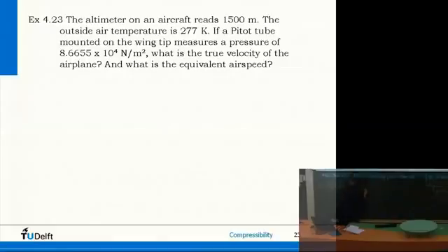So this says V squared is P0 minus P divided by rho. So we have the pressure difference, P0 minus P, P0 from the pitot tube and P. What about rho, density? What would you do with density? Equation of state. Yes, very good point, because the temperature is given, right? You might be tempted to look in Appendix A for the density as well, but we have more information here. So the more actual information you have, you should use it.